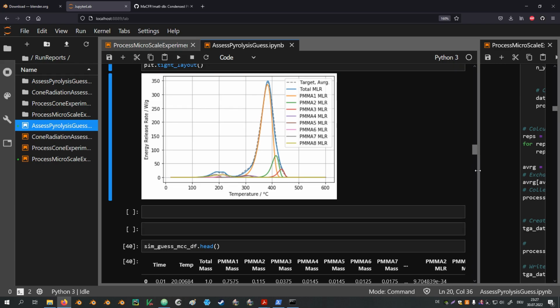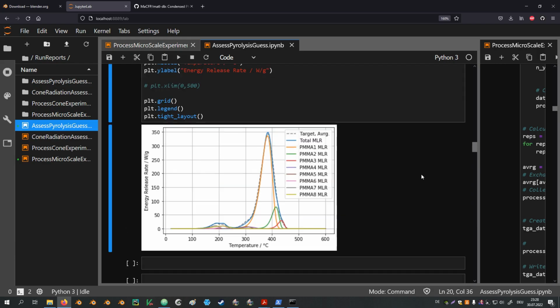Now let's have a brief discussion about the reaction order. As mentioned before, when using the reference values, the reaction order is assumed to be 1. If you wanted to change the reaction order, you would need to provide the Arrhenius parameters themselves, meaning the activation energy as well as the pre-exponential factor. So since FDS is computing these parameters, the question may arise, how do we get to them? For that, we would need to look into the .out file.